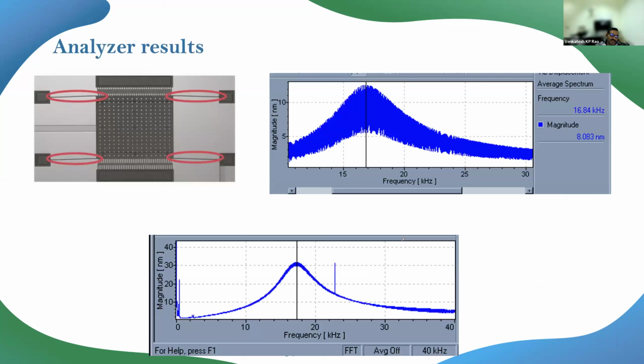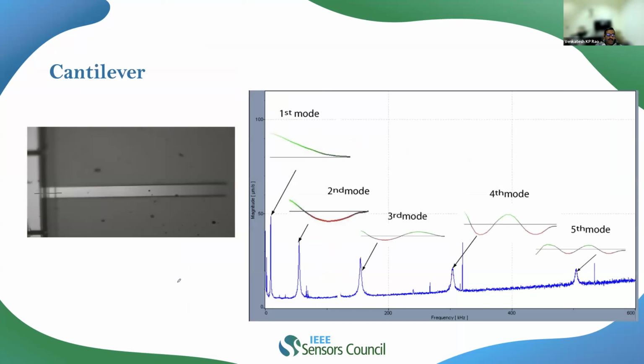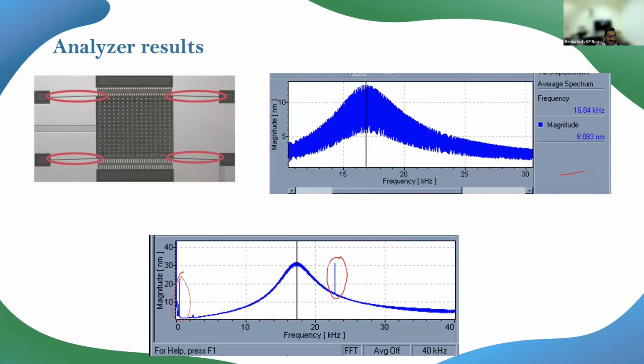Now, before that, this was basically now I have applied the signal, right? Now I want to go to the post processing. In the post processing, we can measure the frequency response of the structure. And during the post processing, we need to be careful about the peak picking. Even if we do get stray peaks like this, we keep in mind how to identify whether that is noise or the signal from your structure at all, right? So that should be kept in mind, right?